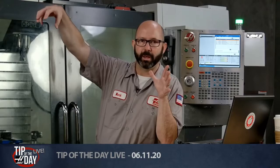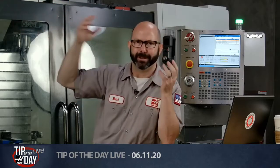There's all kinds of bad things that happen with G28. It's kind of an antiquated code that was necessary back in the good old days, and it just doesn't do what most people think it does. If you command a G28, G0, Z0, it's going to move to Z0 in the currently called up work offset, which might be G54. It's going to move to G54 Z0 before going home, which means it's going to crash into something probably and then go home safely, which makes no sense.